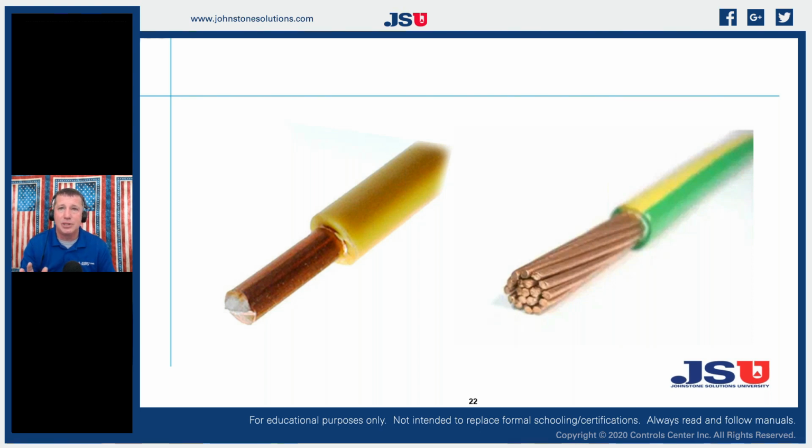We'll do a separate class just on understanding grounds and testing and verifying grounds. But we need to know that the difference between the copper in a solid strand and in a true stranded wire is that our current flows differently through them and we communicate differently through them. So a solid conductor works well as long as we can pass our signal on its surface, as long as there's no corrosion there. A stranded wire works better because we have more paths for that current to flow on.